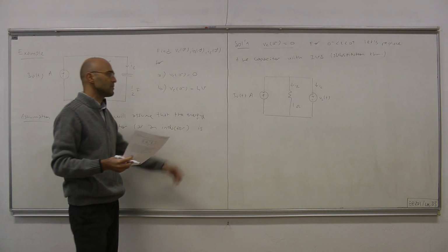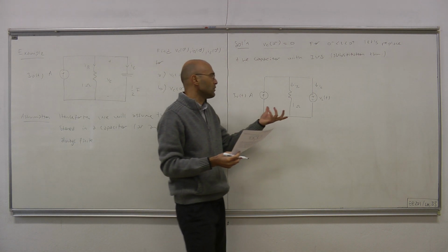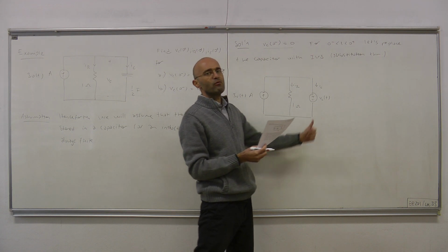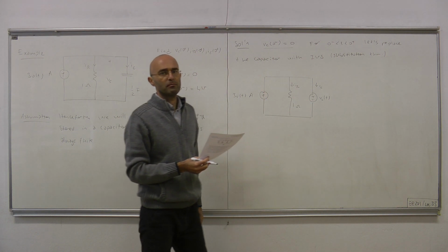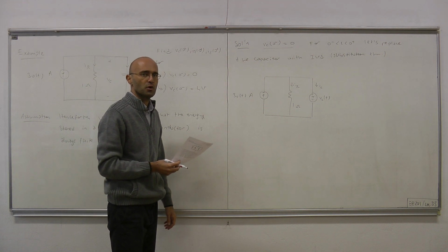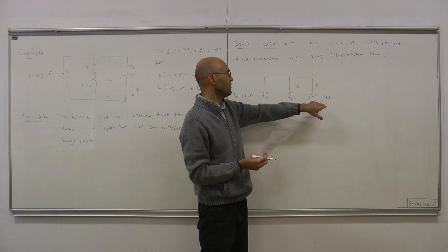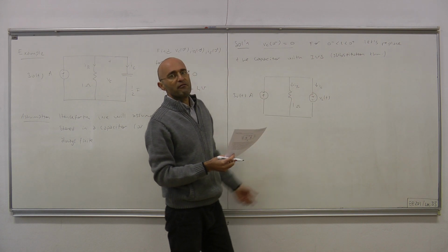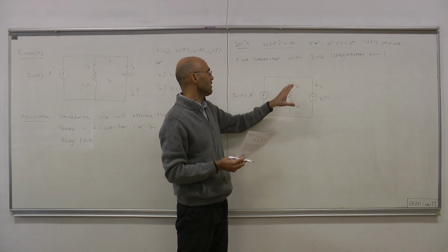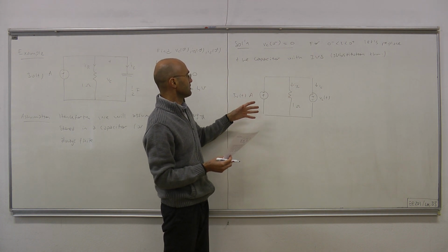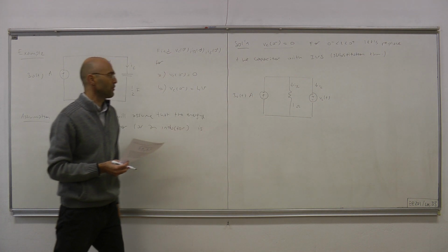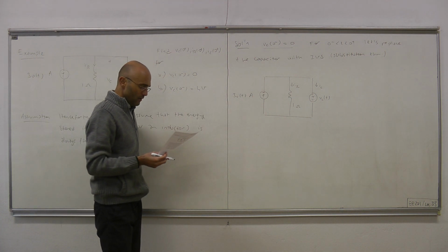But whatever it does, it will have some voltage, and that voltage is the voltage given by this independent voltage source after the capacitor is replaced. And thanks to the substitution theorem, the rest of the circuit will not feel any difference. Everything else will be the same: IC, IR, and this is also already 3 u(t).